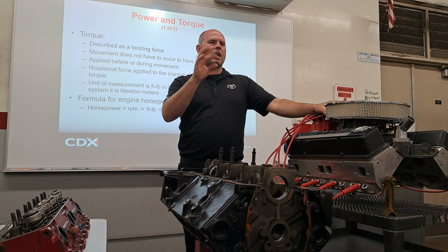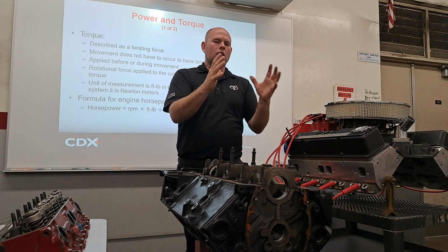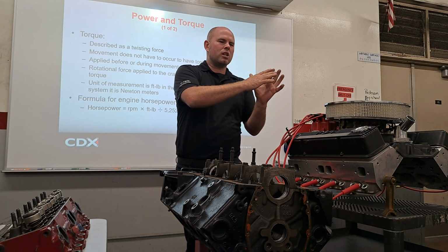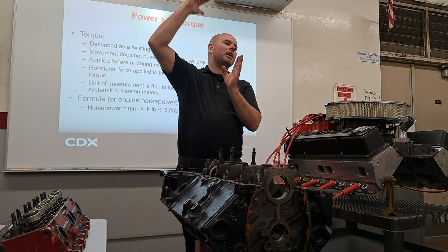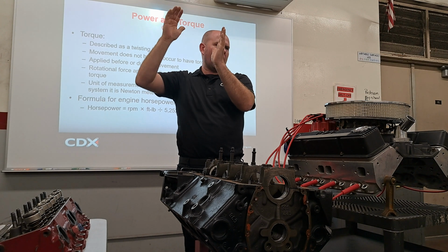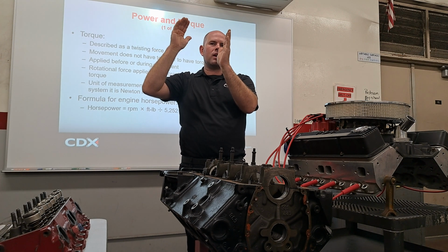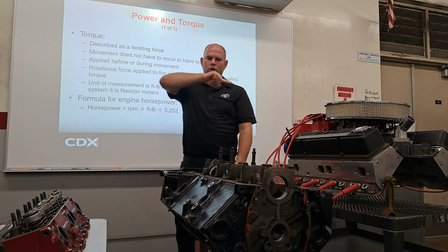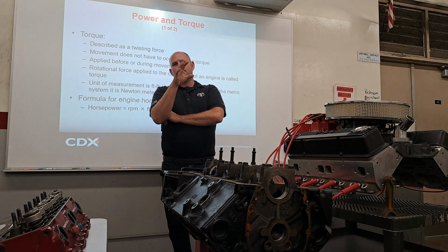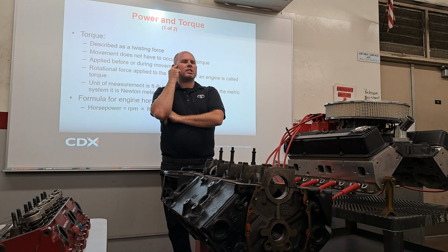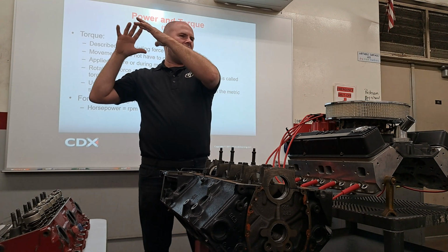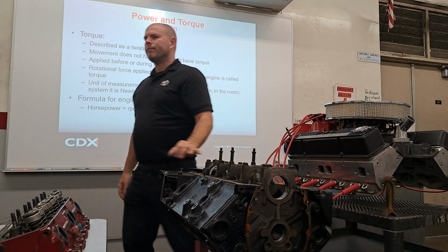Depending on how that engine is made, a diesel has a nice meaty, low, torquey power band. A small four-cylinder like that, sluggish. Way up here at the top RPMs, got a good power band right there. It can do more work right there. Power, we add time in, right? It's kind of weird. You can look at the torque curves of like a dyno and be like, oh, that's kind of what I would like. I could go either way, but in your mind, I want you to think about later. You want something with a lot of low-end torque, or you want something with a lot of high-end power. I want you to think about that. That's a good assignment for you.